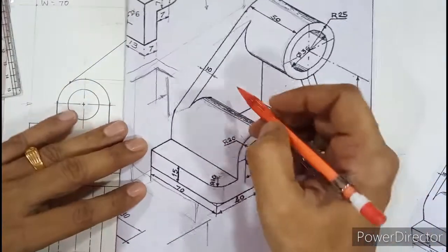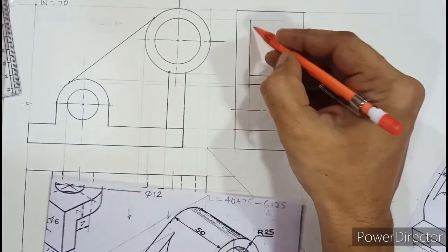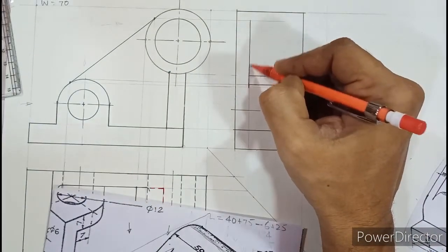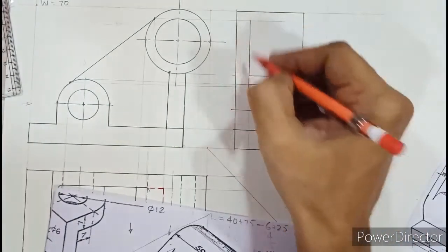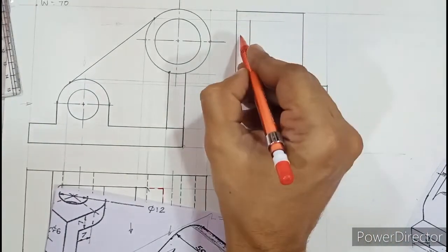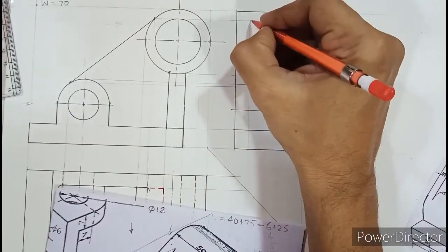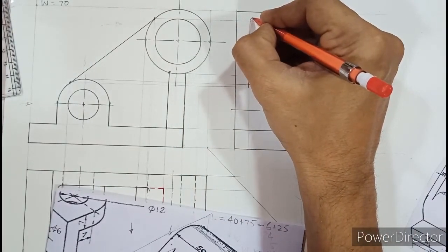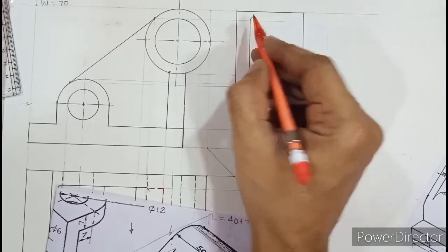Now as you drew the merging point, the merging arc, in the top view, similarly in the side view, if you look here, this dark line is not intersecting any of the dark lines, whereas other dark lines are intersecting some or the other. It means here something is missing. So a small surface of 10 mm is merging with a large surface of 50. So a freehand arc beyond the straight line, this projected line, beyond this line you need to show an arc.